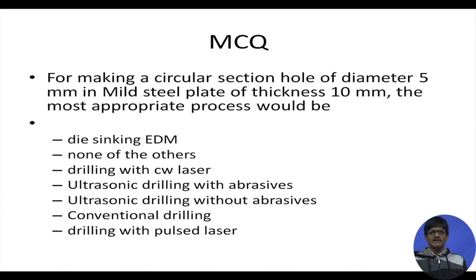First of all, die sinking EDM. Should we use that? Well, it can be used. There's no harm in using it, but we have to first find out whether there's any other competing process which proves to be more convenient. None of the others means that you think that none of them will be applicable. No, this is obviously not correct. Drilling with continuous wave laser. What's continuous wave? Continuous wave means that it's not pulsed, but the output power level of the laser remains constant with time. Do we use that? Well, let's go ahead with the other options.